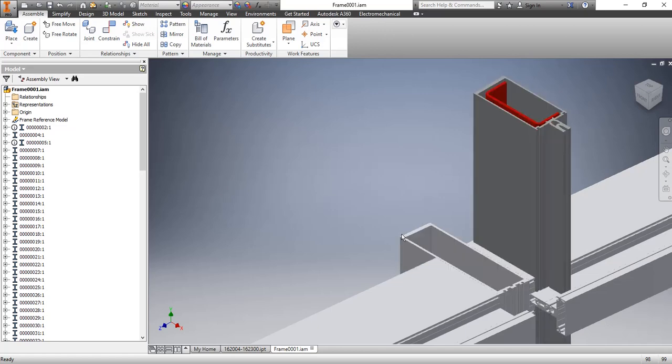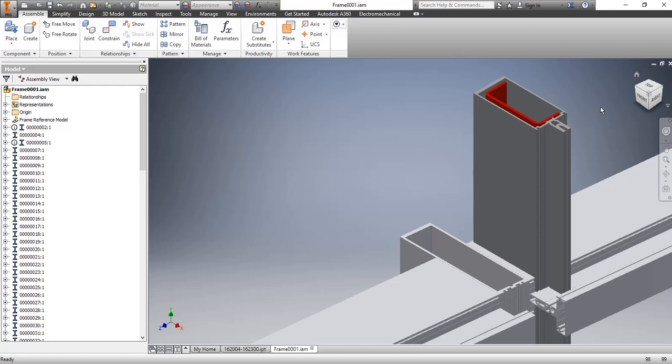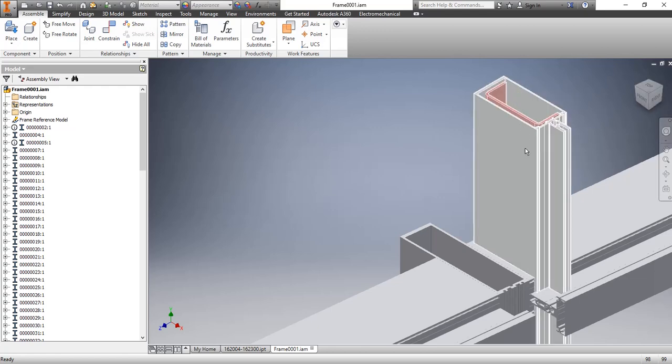Which one you use is up to the approval of the architects, or which one you prefer, because insert steel needs more labor for fabrication, since you have to screw the steel together. You also need more installation hours, since these insert steel verticals are heavier than the typical ones.